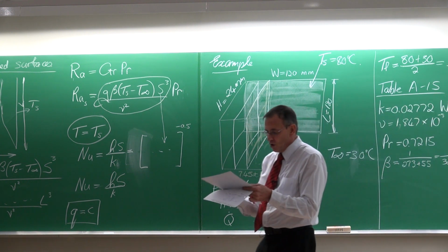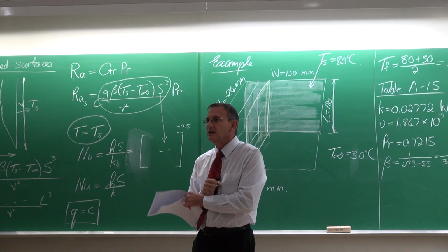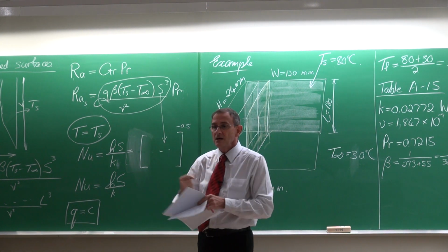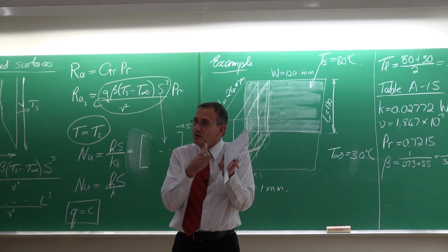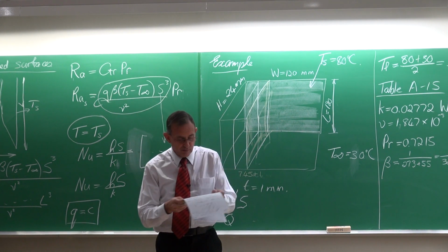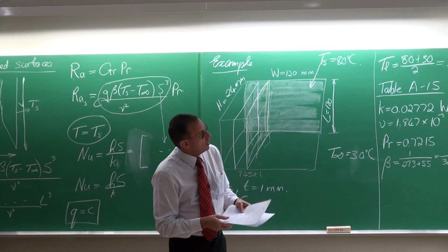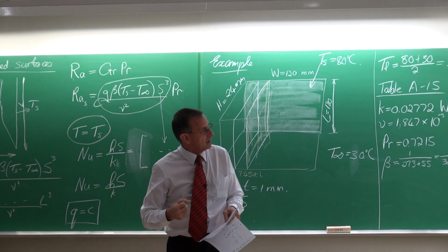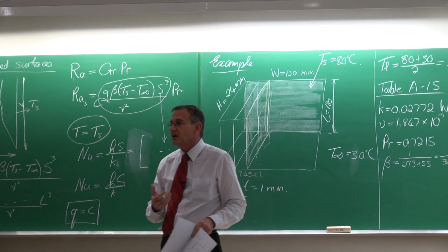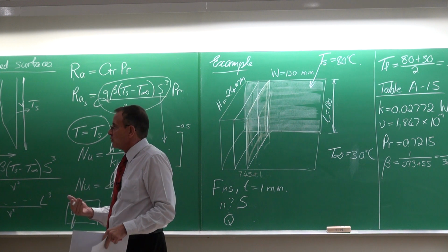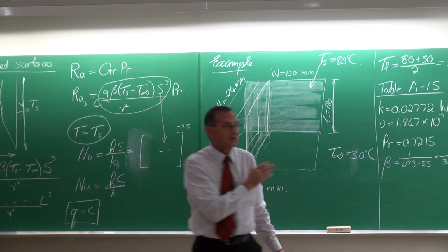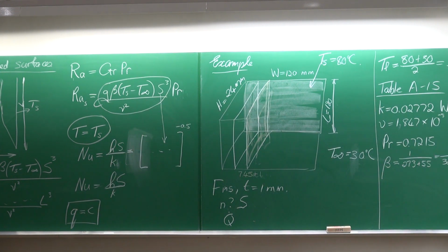And that would give the optimum heat transfer rate that we can get out of that area using the optimum spacing of the number of fins. So if you go onto that area and you put in 28 fins, the heat transfer rate will be lower than this value. So we also have to calculate the heat transfer rate.